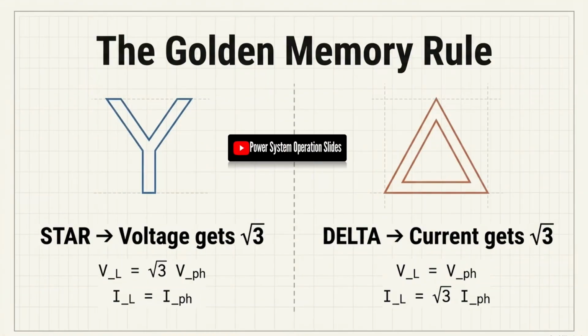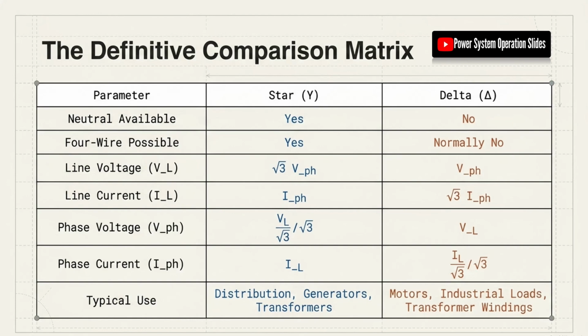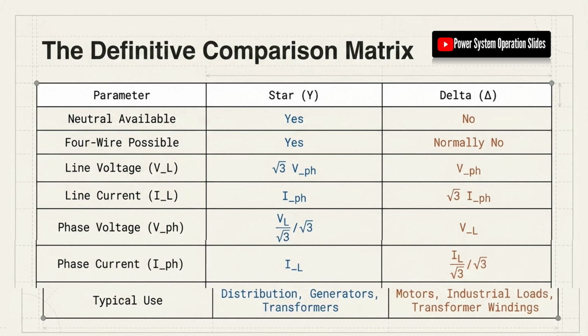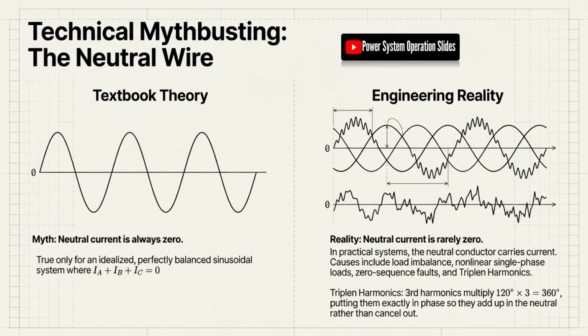Historically, ungrounded delta systems were used in industrial applications where continuous operation was particularly important. Since an ungrounded system does not provide a direct low-impedance path for ground fault current, an initial line-to-ground fault may produce relatively limited current and allow the system to continue operating temporarily. This characteristic was useful in continuous process industries where an unexpected shutdown could cause substantial operational and economic consequences.